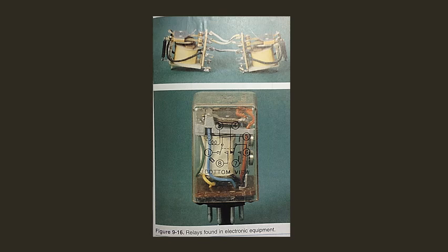The coil is the most vital specification. The coil chosen needs to produce a large enough magnetic field at its rated voltage to ensure positive contact of the switch points at all times. However, most relays are so sensitive they require only a milliampere or less to energize, so care must be taken.